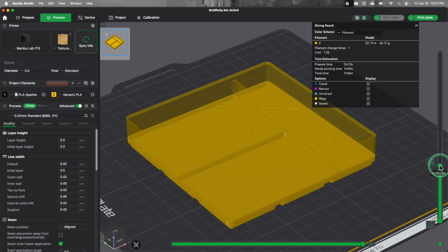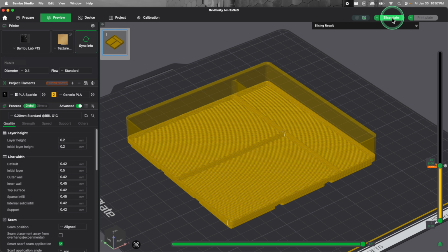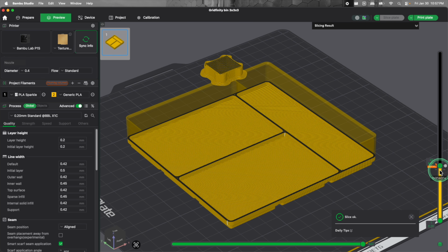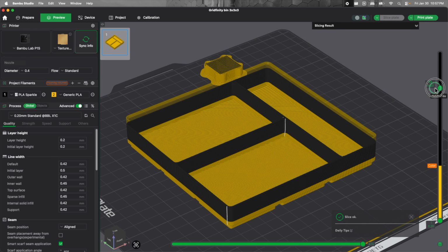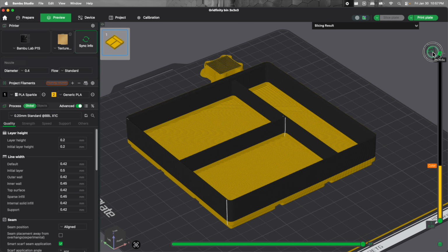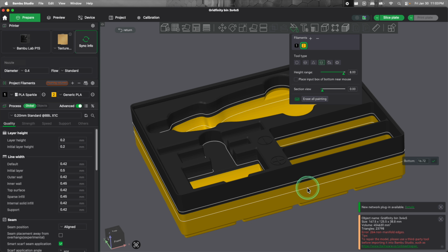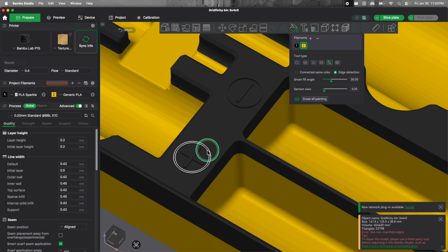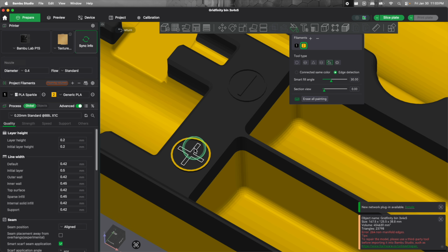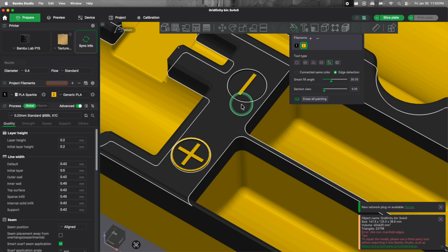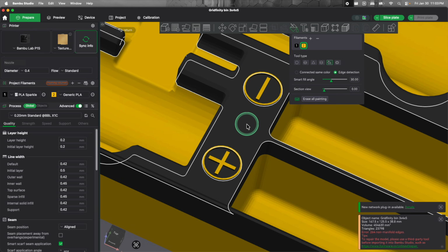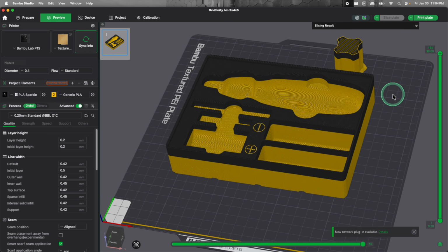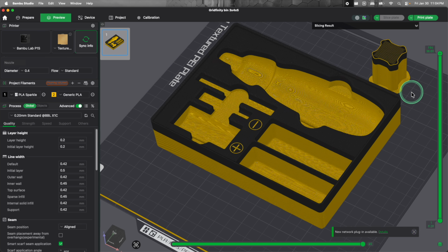This will tell your 3D printer to either swap colors in your AMS or equivalent if you have multi-material extrusion, or for a single color printer like my P1P, it will stop the print at the height and give me the opportunity to change the filament out manually to finish the print in the second color. The hybrid approach to this is just using your color tool in your slicer and setting a height range for your primary colors. Then if you need to also have multicolor blended into your design like I did with my ratcheting screwdriver, you can also just paint specific small features to give you the ability to still save some color swaps and use it only when needed.